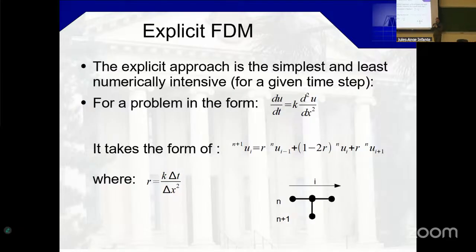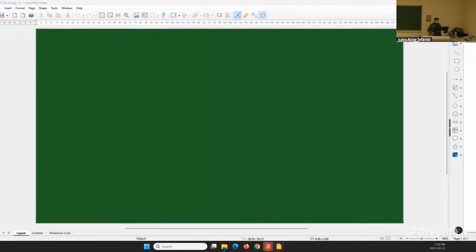And so you might end up having different values of R in different directions, but whatever is in this term must always be larger or equal to 0 for the explicit finite difference method to work. But for one material, we're setting that as 1/2.